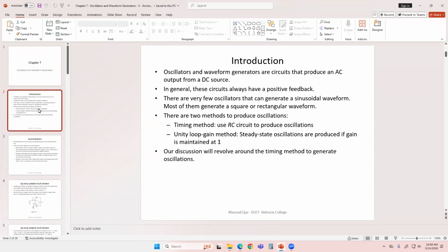Circuit analysis, lab number 5. You created a filter to extract the fundamental component from a square wave. I know that because I wrote those labs. So if you do need a sinusoidal waveform, you can always extract the fundamental component, or any harmonic if you want a different frequency, to get the sinusoidal waveform from a square oscillatory waveform.